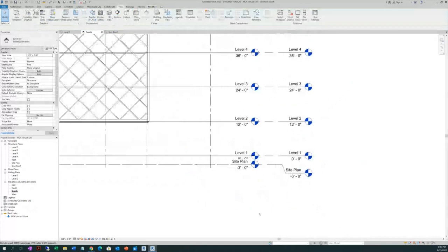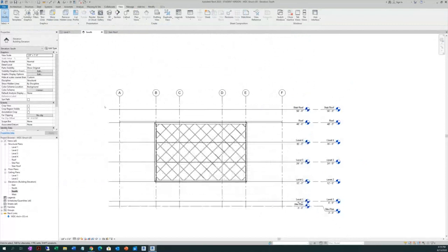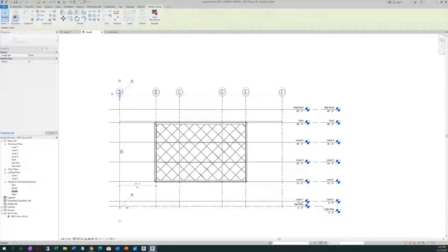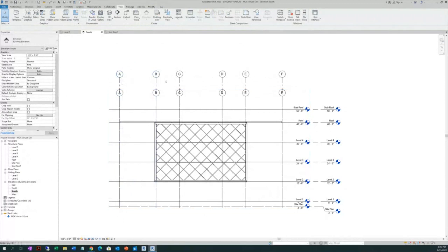Something like this, correct? Now, why don't you ask me what happened with the grids? You just mentioned that we just copied the grids. Click on one of the grids and pull it up. This belongs to the link. These are your grids that you just stole from the architect. That's the way the structural gets the grids, gets the levels, and coordinates. Okay? We haven't finished yet.